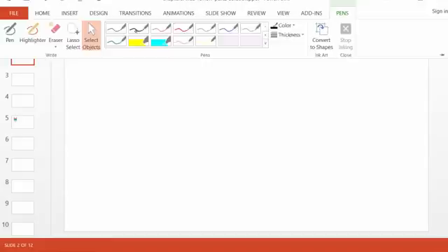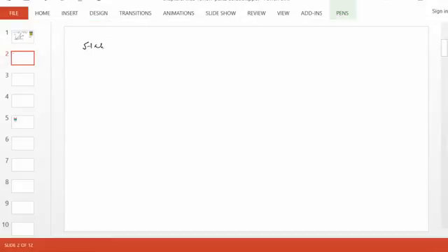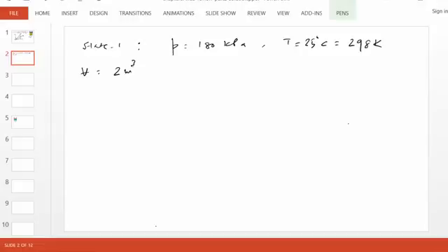Okay, so let's begin by evaluating the beginning and final state first. What is known is that for the beginning state, let's call it state 1, we have been given pressure, temperature, 25 degrees Celsius. Let's convert it to Kelvin. And I think the volume is supplied. So we know we are going to need the mass. So quickly let's apply the ideal gas equation of state, PV equals RT. And recall, for air we are going to use R equal 0.287 kilojoule per kg Kelvin.